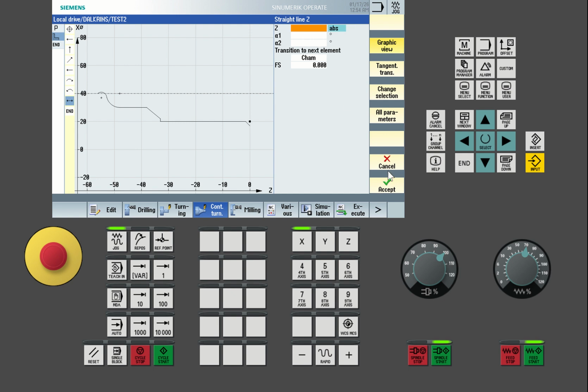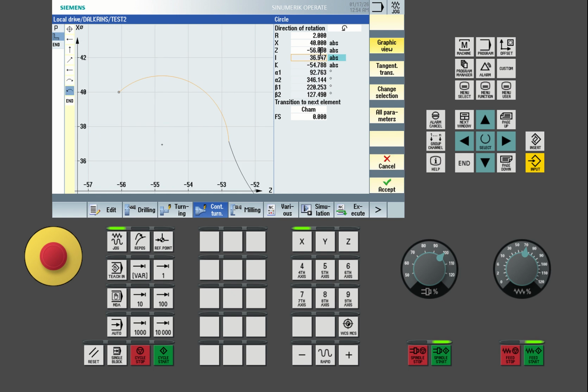So this one I want to change this value because the way the curve is not good. So it should be 56.08 subtract 3.29. I should get 52.79. So from this I have to add plus 1.92. So here should be minus 54.71, so that we get the correct curve. You see now this is a correct curve.